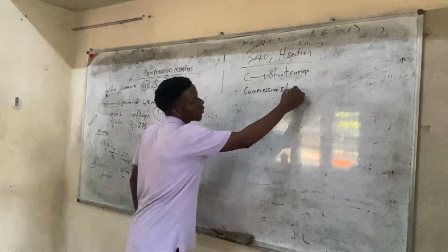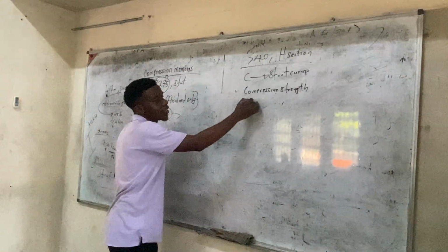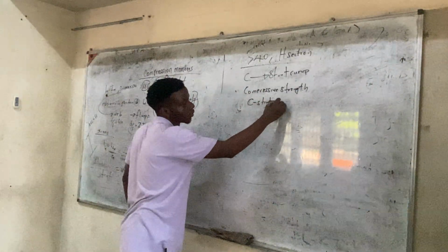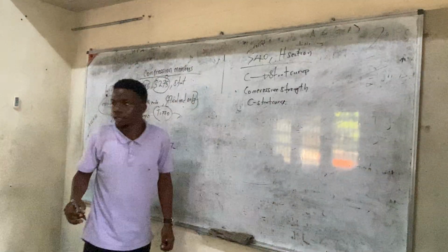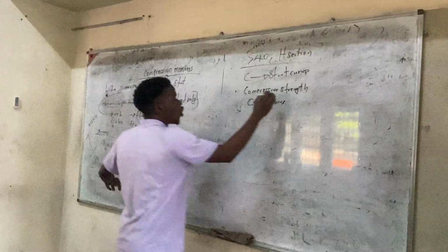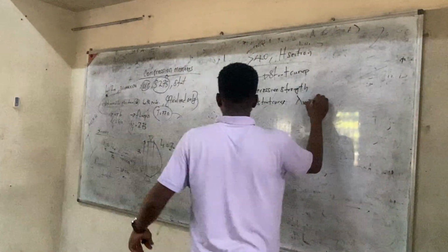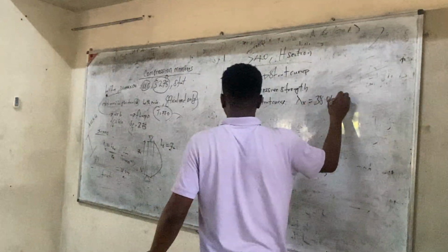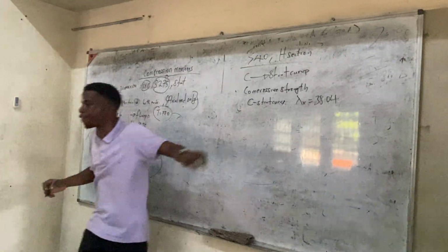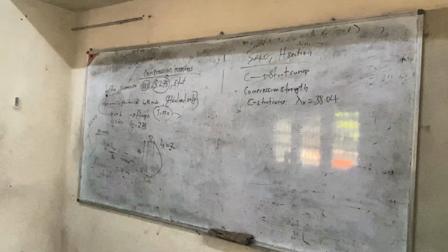Lesser than 110, okay? Yes, carry C, the short curve of C. It's C for the x-axis. Carry short curve of C and slenderness ratio of 38.4. So it's less than 40. Carry these two parameters to table 24. You interpolate. Yeah, we will calculate.